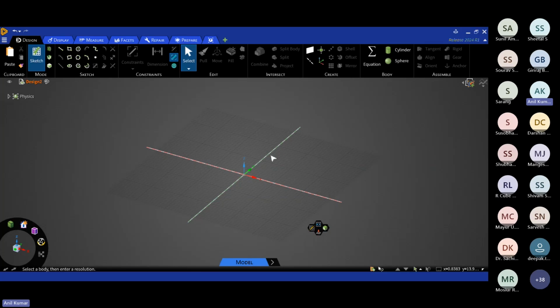So if you talk about structural capabilities using Ansys Discovery, we can perform static structural analysis. We can find out the model natural frequencies, up to 12 mode shapes. We can apply different types of loads like pressure load and bolt pretension. We can consider the contact nonlinearity also.